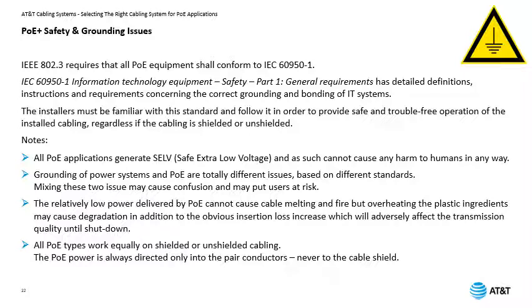The relatively low power delivered by PoE cannot cause cable melting and fire, but overheating the plastic ingredients may cause degradation, in addition to the obvious insertion loss increase, which will adversely affect the transmission quality until shutdown. All PoE types work equally whether you are using shielded or unshielded cabling.